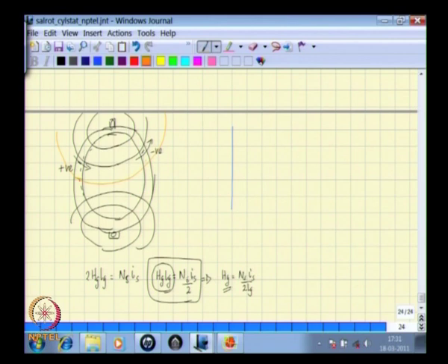So what we have is, if you now plot the actual MMF variation around the circumference, this is your angle alpha as you travel around the circumference, and this is let us say MMF. This MMF is constant at a value equal to Ns into Is by 2 as you move around alpha.